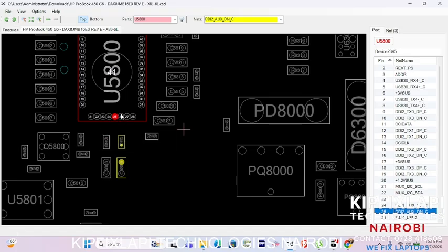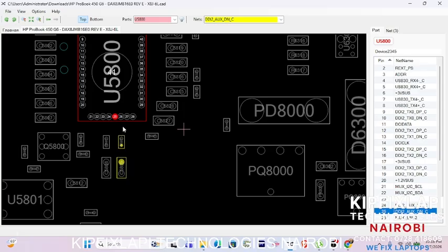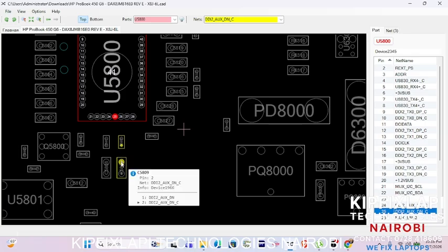Now you've replaced it with a brand new IC, which of course has pin number 25, but there's no track to connect pin 25 to the other lines where it is needed. So you should be able to loop a wire running from pin number 25 and connect it here to pin number 1 of this resistor, and also here to pin number 2 of this capacitor. That is how this board view file can help you to fix those problems.